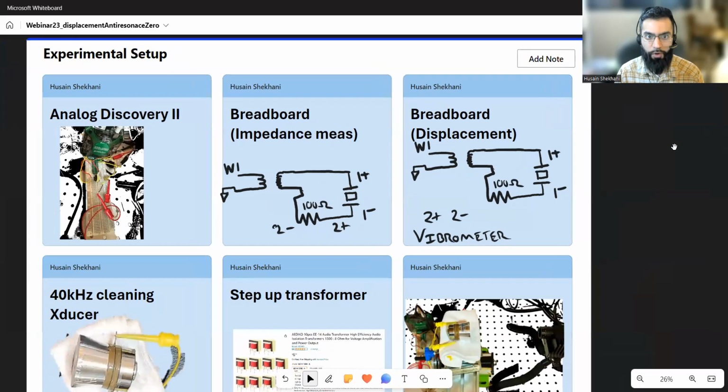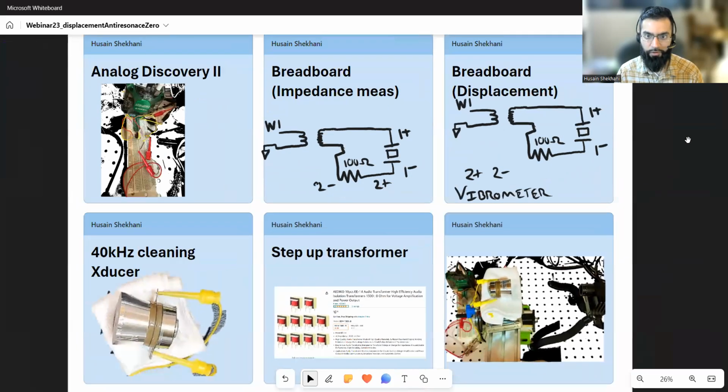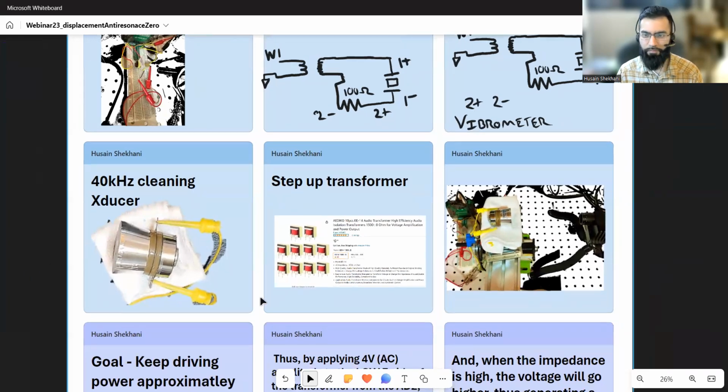Typically with a normal oscilloscope, you have to reference to ground if you're using normal probes. And if you have to reference to ground, then your voltages are going to get messed up because you're going to need a math channel for voltage measurement. So you have to use all these different settings and stuff, but we don't have to do that here.